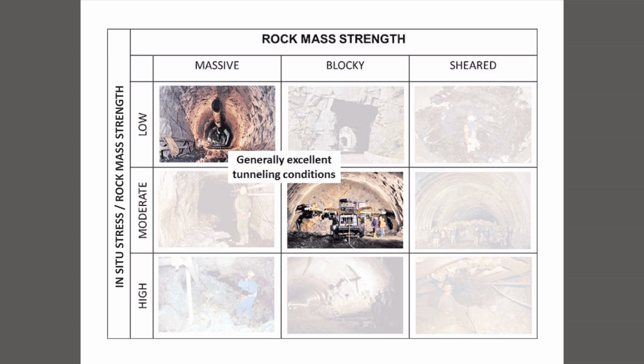So let's break this down into some simpler elements. The first one is shown here as generally excellent tunneling conditions, or you might call it the sweet spot of tunneling. If you're lucky with your tunnel, you might get to work in these conditions occasionally, where you're either in very good intact rock or you're in jointed rock, but where the stresses are high enough to clamp it, but not high enough to break it. And so those are very good tunneling conditions.